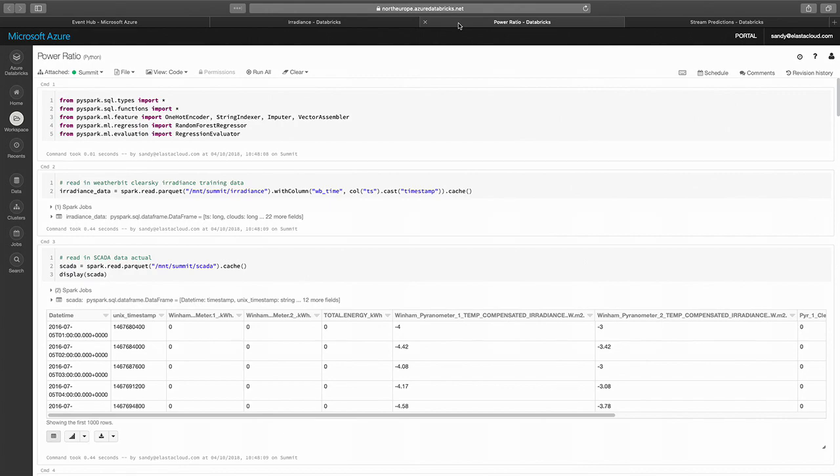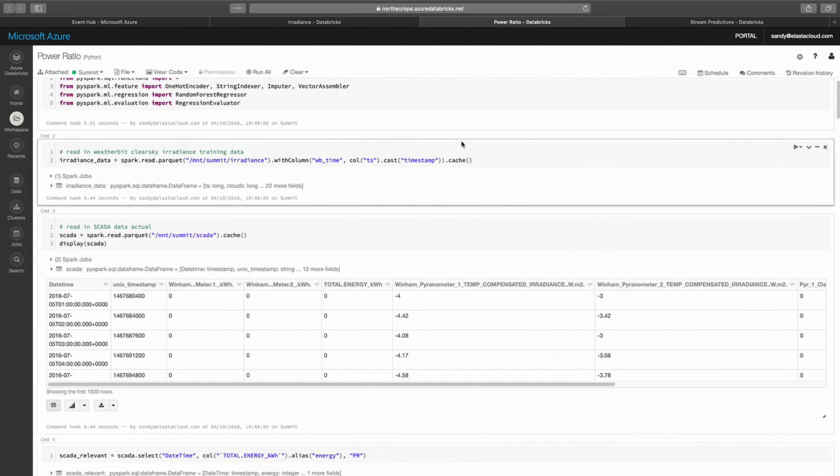Solar farms are different in terms of how well they change irradiance to power. Part of this is to do with age, and part of this is to do with the manufacturers and the different solar panels they have, and inverters and aspects like that. One of the issues we have with predicting irradiance and power across the entirety of the UK is if we don't have access to a solar farm's actual data, we can't say how efficient they are at turning irradiance into power. That's one of the hardest parts that we have without that data.